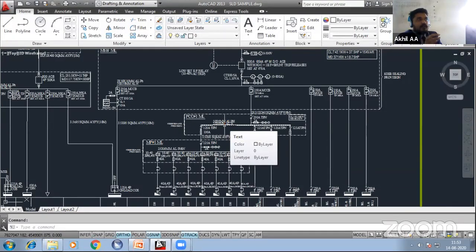There are 22 floors, right? If you are taking a metering panel for each floor, a metering panel means it will have an energy meter inside. For apartments, we have to provide energy meters, right? That is why it is called a metering panel. If you take metering panels for each floor, you might have 22 or 21 metering panels. All these metering panels you cannot directly connect to the MSB, because the incomer rating of the MSB and the outgoing rating of the MSB should have a relation, 1/3 or 1/5. You cannot go down beyond 1/3 or 1/5.